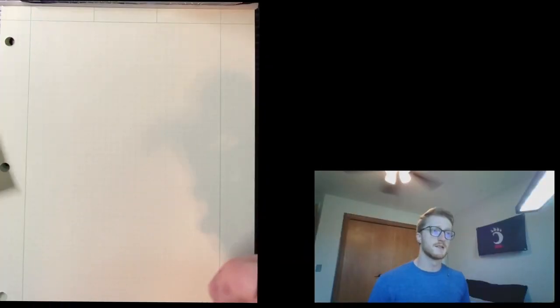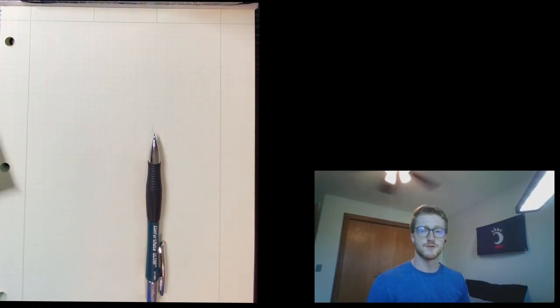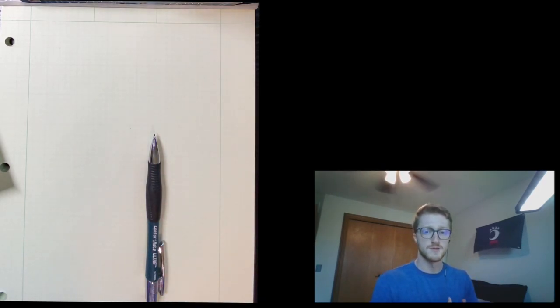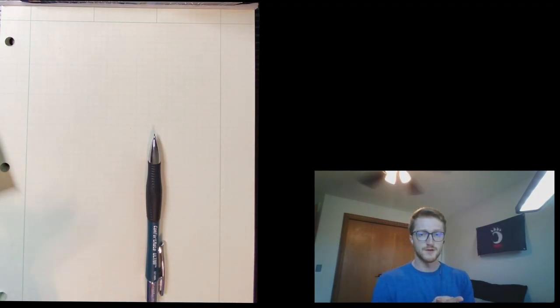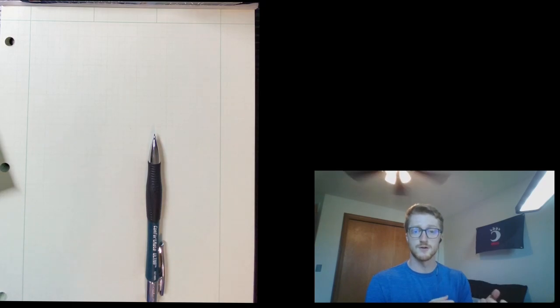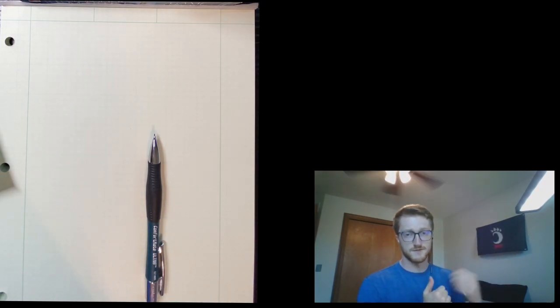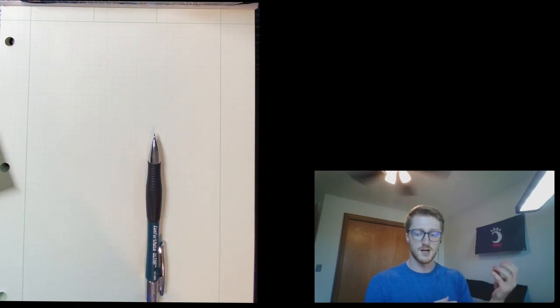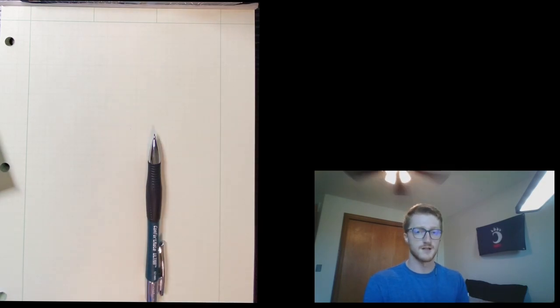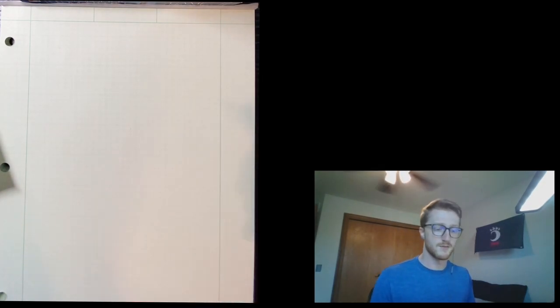In this part, I'm going to be explaining how you can use the Lewis relation in a part of an energy balance for a wet and dry bulb temperature experiment. So with the wet and dry bulbs, you have a wet bulb, and when you swing it around wrapped in a cloth, the water on the wetted bulb is going to evaporate, and the temperature on that bulb will read lower than that of the dry bulb because there is evaporation occurring, and the heat is supplied to the water from the air in order to cause it to evaporate, and therefore it will read a lower temperature because of the evaporation.